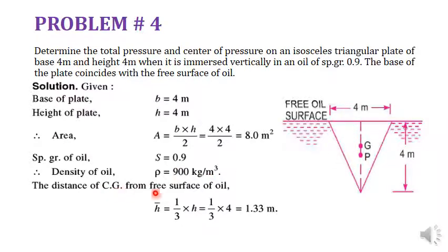The distance of the center of gravity from the free surface of the oil, h bar, again needs to be calculated. Now you need to be very careful whether your base has contact with the free surface, or the tip, or the top of the other side of the triangle has contact with the free surface, or it is submerged in the water at a certain depth. Okay, now in this particular case, if the base has contact with the free oil surface or liquid surface, then this center of gravity is going to give you